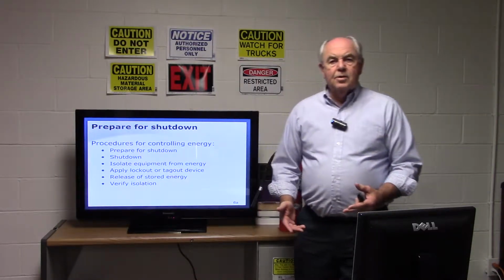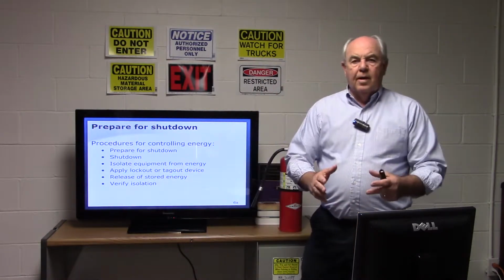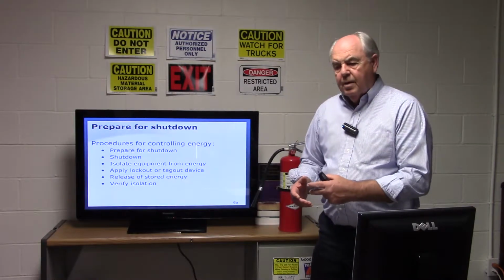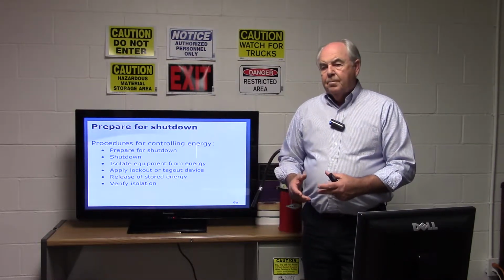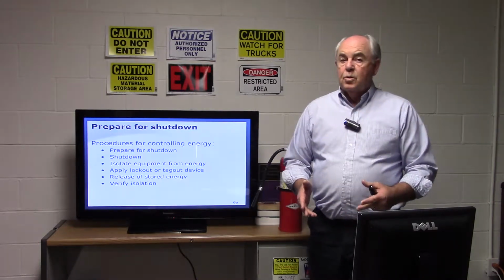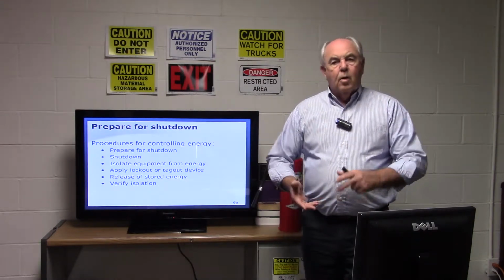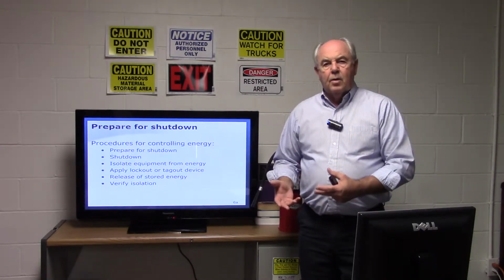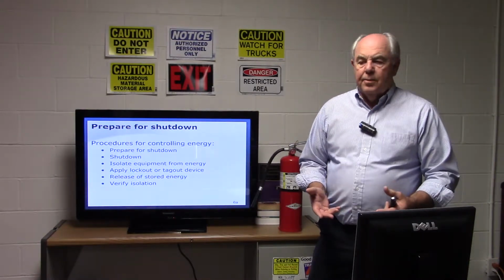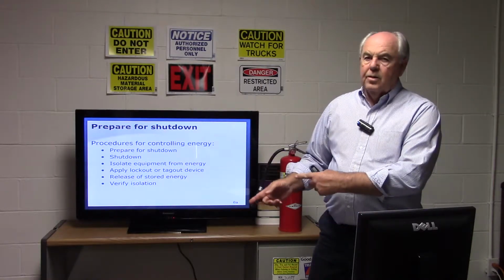The easiest way is to hit the start button. Once you've done these procedures and you have everything shut off and you've verified it and you have made sure you've de-energized the equipment, hit the start button. If that machine starts up, there's another energy source coming in. Now, there are occasions where the machine might jog or it might rotate, because sometimes you have a large capacitor in there that could store some energy and you may have just de-energized the capacitor. Hit that start button again. If that thing moves again, check your energy sources again.